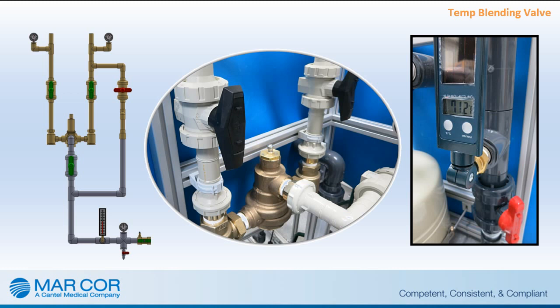Some systems may not use blended water and will run using only a cold water source. Depending on the geography of the location, this water may be very cold in northern locations and very warm in southern locations. This lower and higher temperature will affect the product flow and water quality of the RO membranes. Whether using a blending valve or having a system without a blending valve, the temperature of the incoming water must be within the specifications of the RO membranes and all pre- and post-treatment water components.